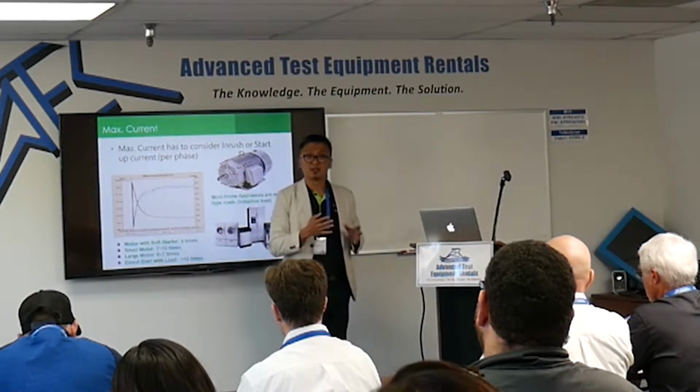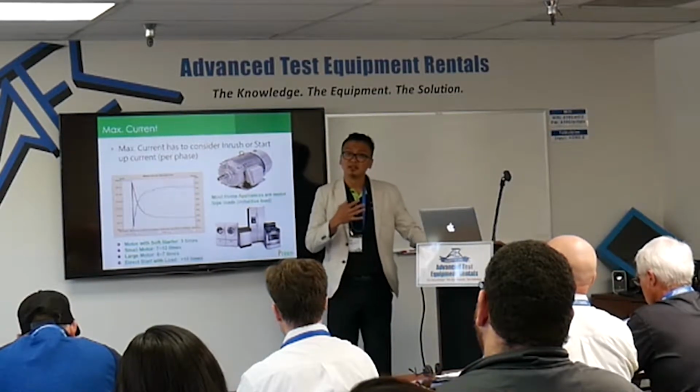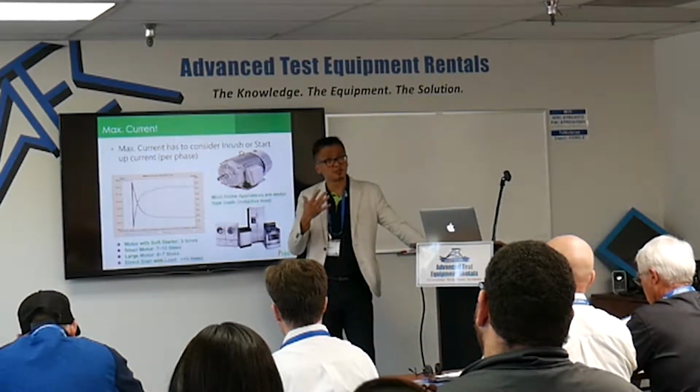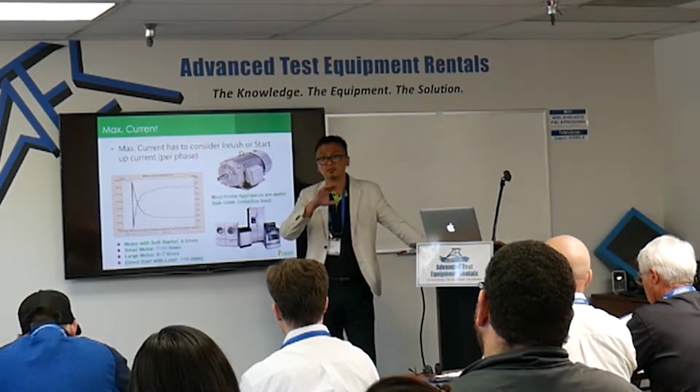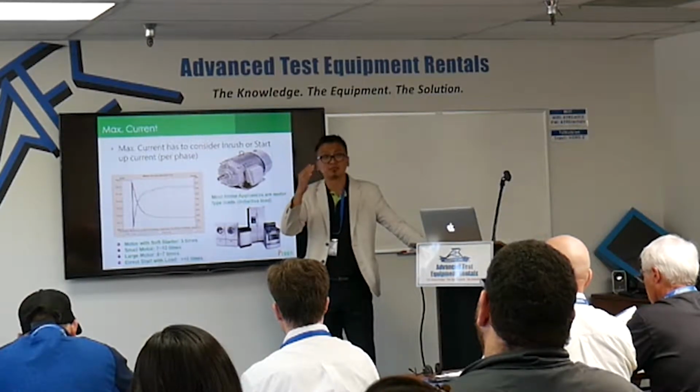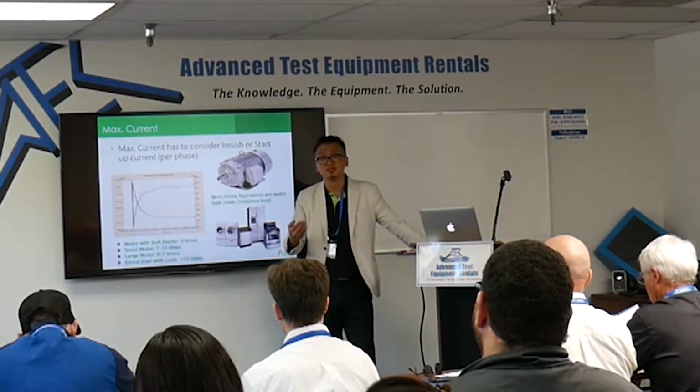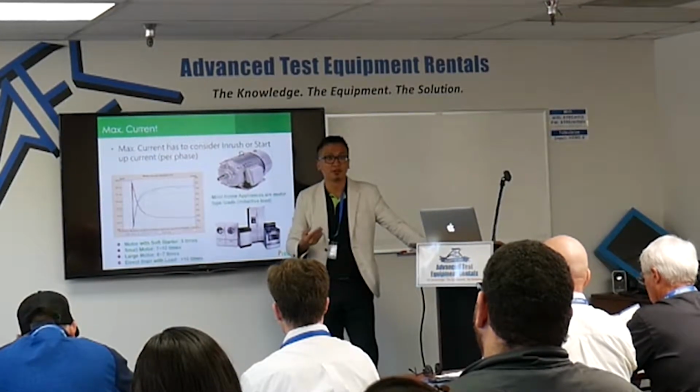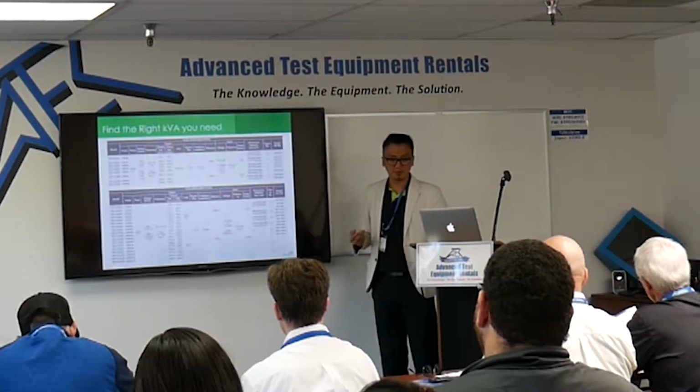A better way is to check what the maximum current is when it powers up, using a scope. That's the best way to figure it out. Okay. Any question here?